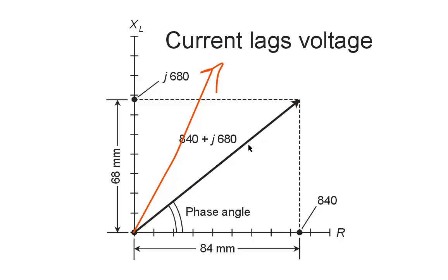As the reactance grows to many times the resistance, these vectors get more and more near this inductive reactance axis, until finally, if we had a situation where the inductive reactance was thousands and thousands of times the resistance, remembering that it's imaginary, we would get the actual axis right there as the vector for the complex impedance.